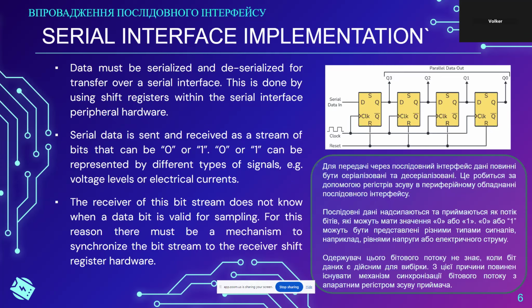Those are some of the logic chips that have D flip-flops that can be used for this purpose. Of course, there are also logic chips that have complete shift registers built in. We're going to talk about those later at the end of the presentation.